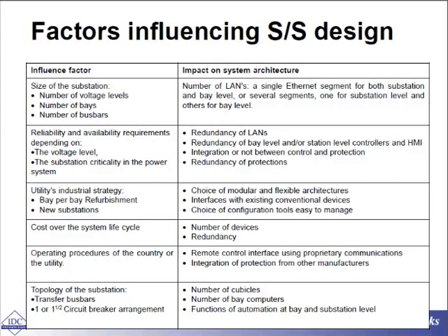All right? How reliable and available are these voltages in your substation? Any bus coupler, circuit breaker, any redundant bus bar, any redundant transformer? How many substations do you have to interconnect together? What is the life cycle of your system? How much of it has been left?